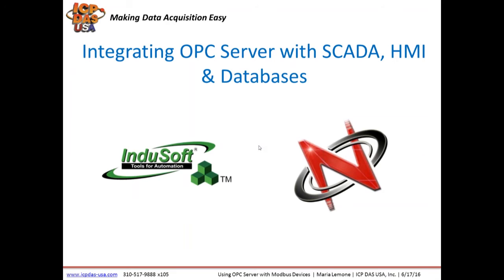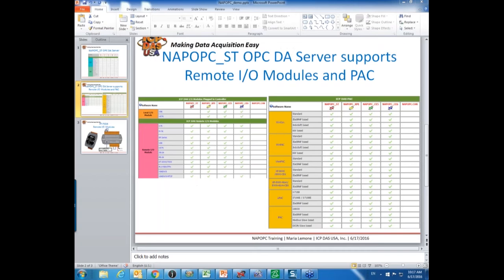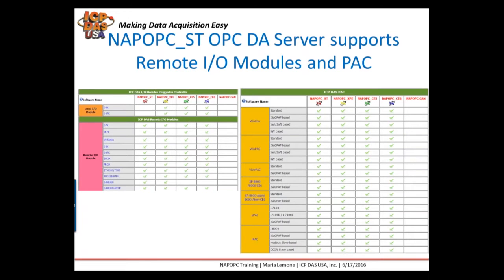One software we provide is free easy data logger software. You can show trend information, gauges on a screen, and bar graphs that show the different measurements. You can also arrange a layout page which shows different objects like gauges, buttons, and text displays to show you the different kind of information you want to see. It also supports web cameras, so you can really customize the interface. This is free software that you can use with our devices. You can also use it with other vendors' Modbus devices as long as you have one of our ICP DAS modules in the network.